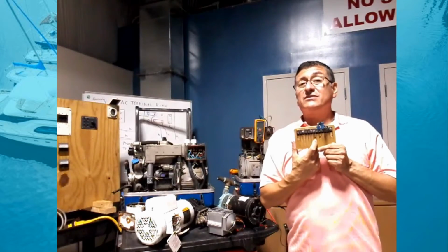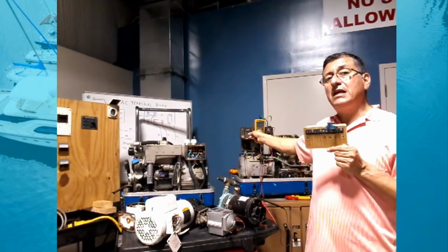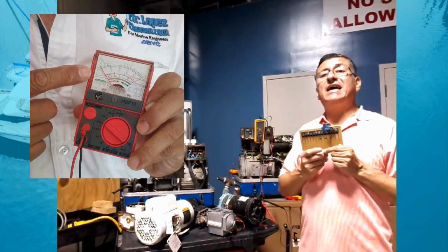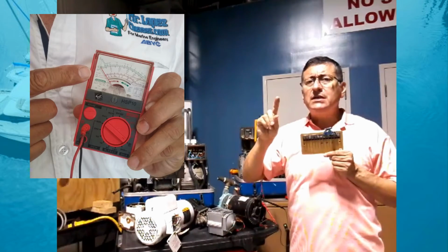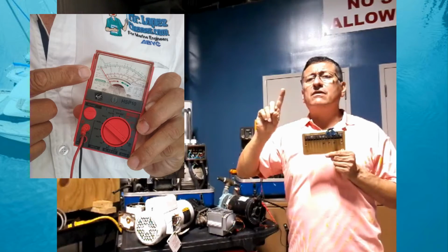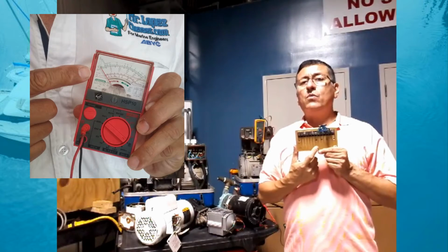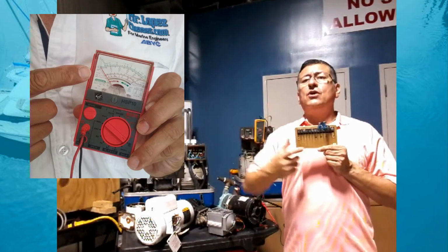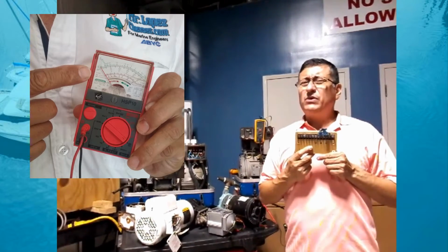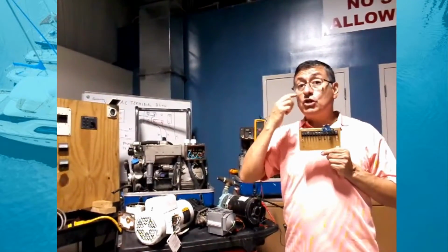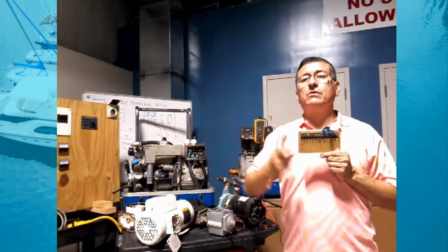To calibrate stabilization, I recommend using an analog multimeter instead of a digital one, because with the needle it is easy to identify whether the voltage is fluctuating or stable. I prefer to calibrate the stabilization with an analog multimeter, because with a digital one it's not easy to verify that the output is perfectly stable.